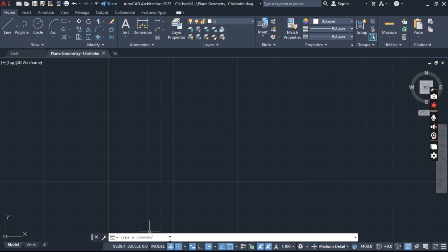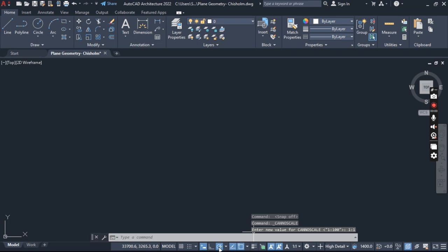All right. In my last video, I said that personally, I don't draw with the grid and the snap to grid points. I turn those off. But remember that you need to have your dynamic input on. Your scale should be 1:1, and then you can decide whether you're using ortho mode or you're using polar tracking.